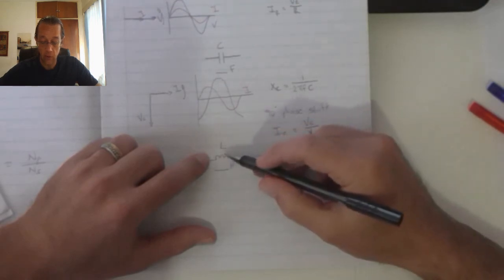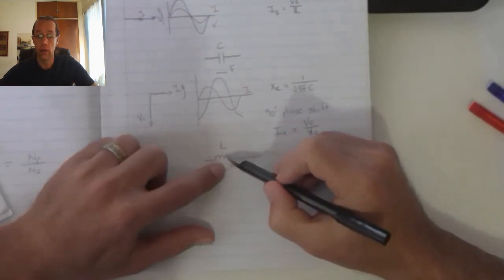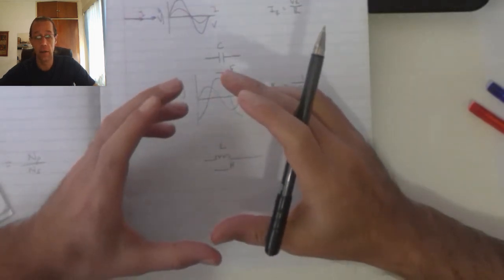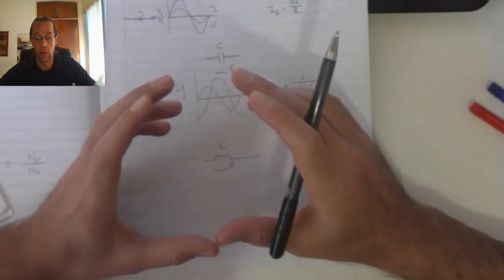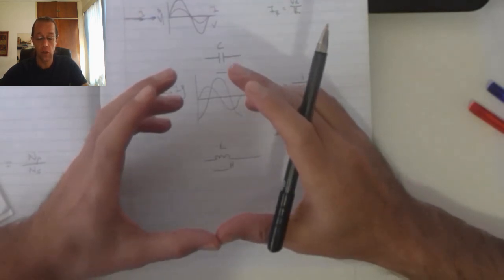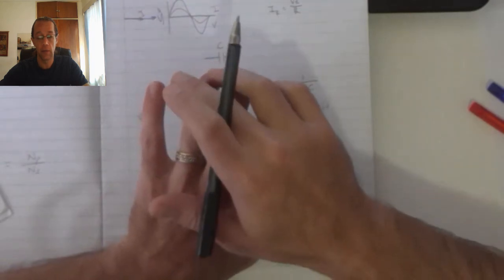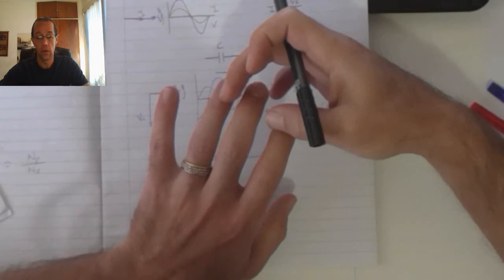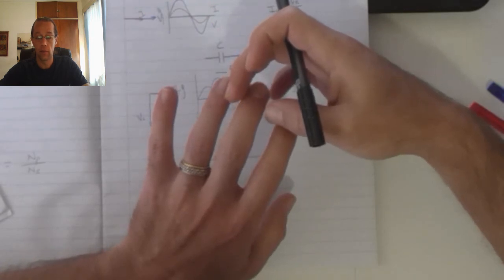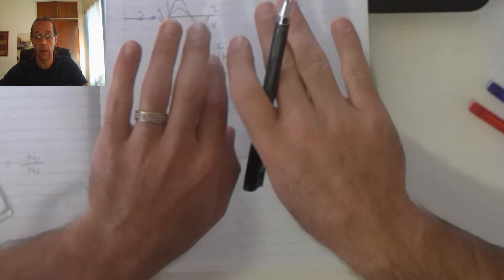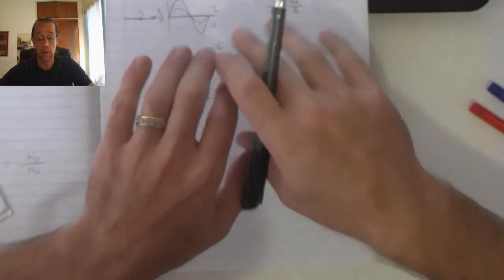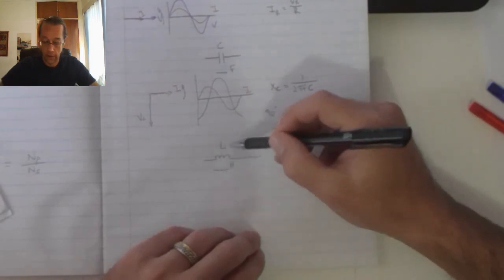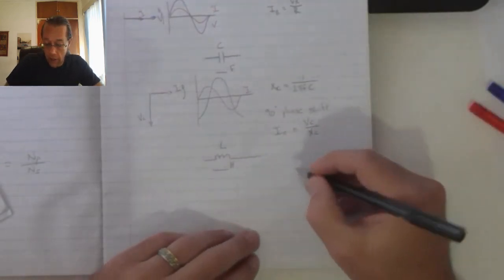So we've realized what happens is when current flows through the coil, each loop generates its own magnetic field. The size of that magnetic field is dependent on the size of the current that's going to flow through that coil. Now, because those loops are so close together, there's no space for that magnetic field to expand. Because there's no space, those magnetic fields are pushing against each other, and because the magnetic field can't expand, that resists the current that's going to flow in my coil.